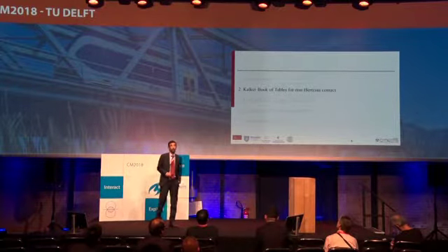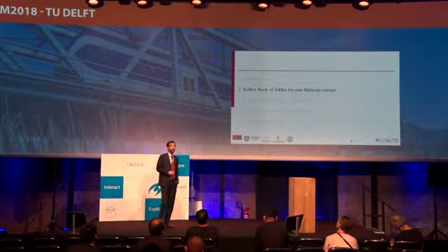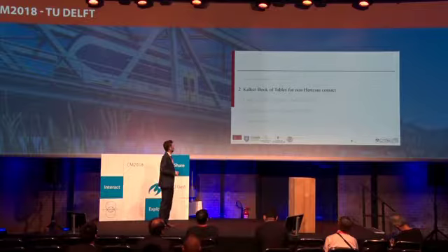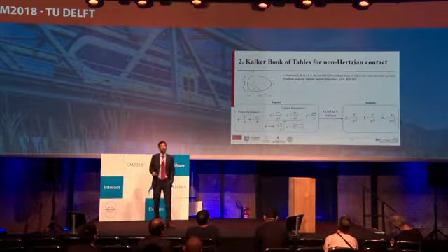Let me first describe how this contact table approach can be done for non-Hertz contact patches. That's some previous work we did in collaboration with Professor Piotrowski in Warsaw, which originated what we call the Kalker book of tables for non-Hertz contact. This has been published already. It's based on a simple approximation of a non-Hertz contact. It's called SDEC, simple double elliptic contact.